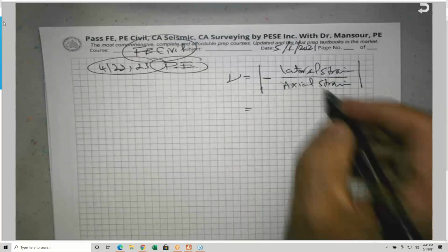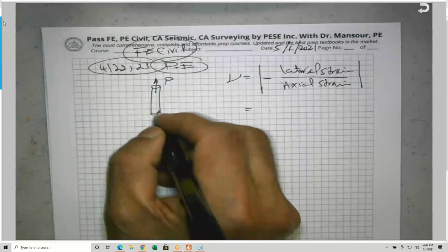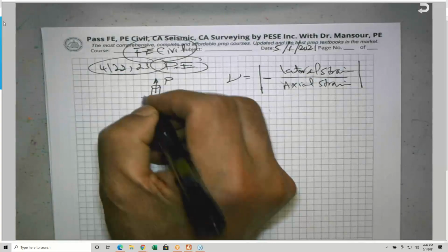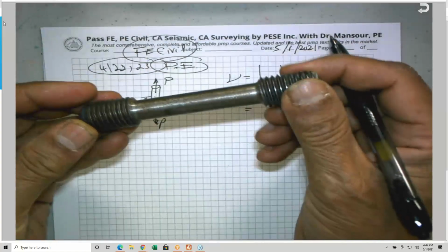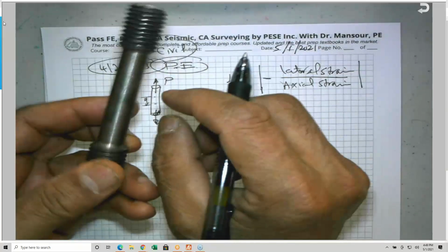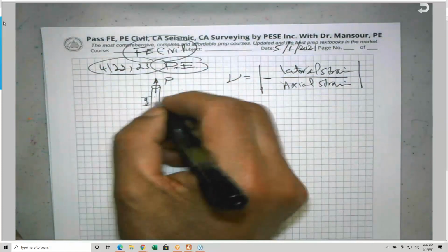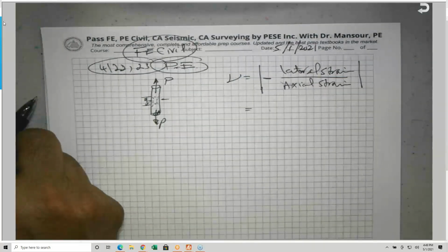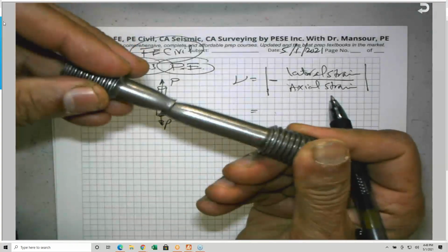Because any material, okay, you apply a tension. So if you have 2 marks, normally we do this in the lab by punching 2 dots on the specimen. This is a tension specimen, for example, with the center punch, for those of you who took the mechanics of materials lab, they are familiar with that. We make a little tiny dent here and a dent here, and the distance between is 2 inches. Okay, it's called the gauge length. So you'll find that there is a reduction in the cross-sectional area. This is getting skinnier and skinnier until ultimately it will fail, like the specimen I showed you last time. This is after the failure. This is how it looks after the complete tension test. So as you can see, the reduction in area, this is what we are looking for.